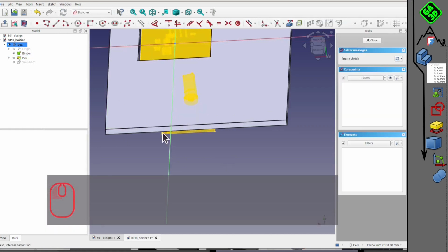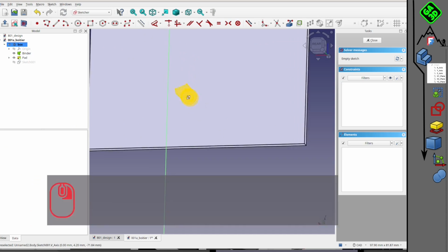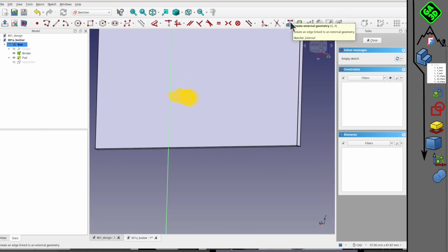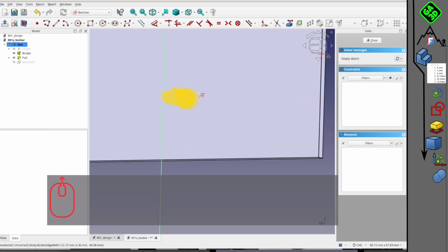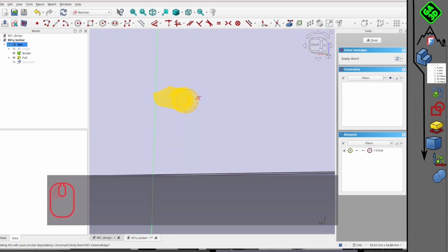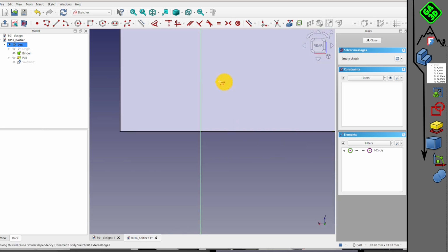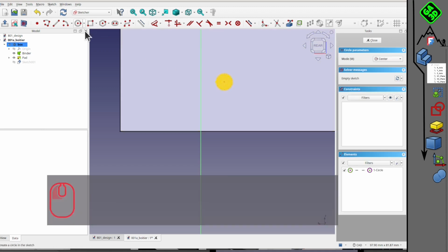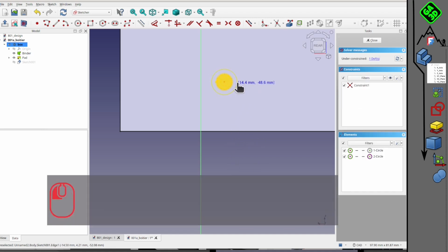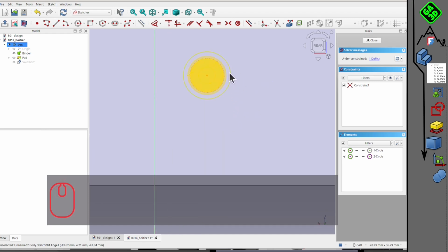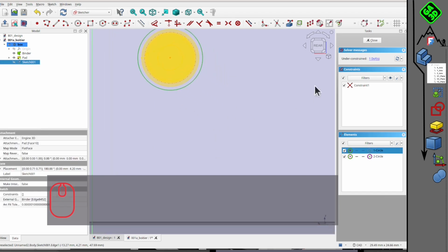When I build 3D enclosures like that, I do this a little by feel, and I see that I'm having a little margin like that, a little wider than the diameter of my encoder. And then we use the pocket tool, and then it dug the volume. So here we are creating our passage. So now what we're missing is the attachment elements to come screw our small electronic circuits.